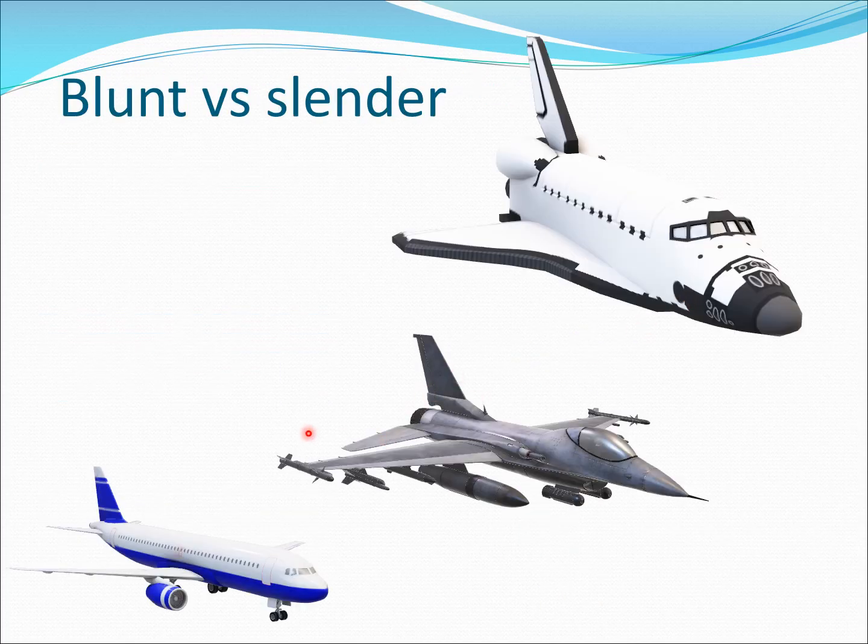So let's now pictorially look at the different types of vehicles we have considered. We saw that when you are in subsonic flight and high subsonic speeds, typically for passenger jets and so on, you have a reasonably nice shape here, which is very amenable to nice flow about the aircraft. However, when we go supersonic, we have this kind of pointy nose, and the reason is that you want a shock wave to form here, and so behind the shock wave there is a dramatic reduction in the airspeed.